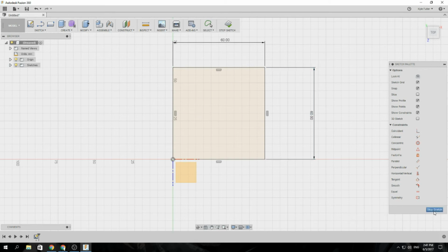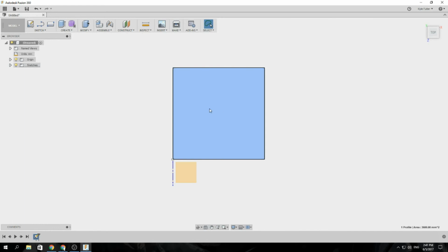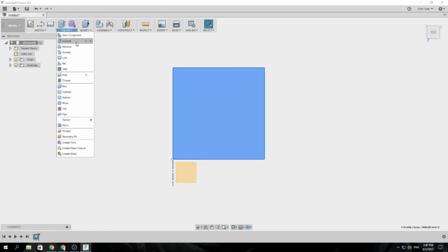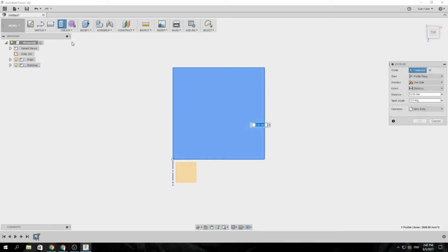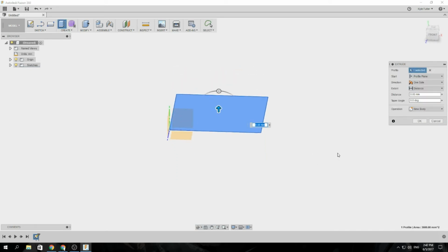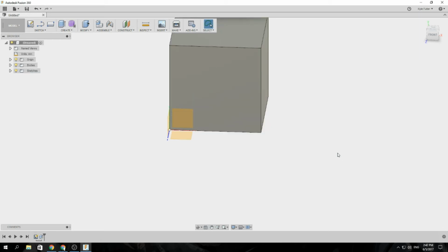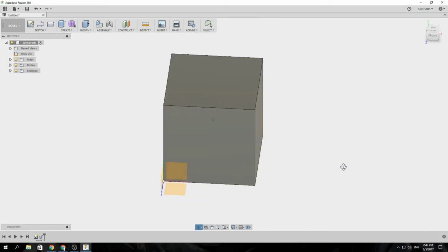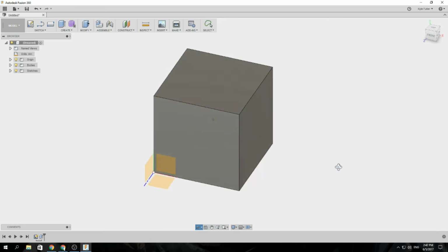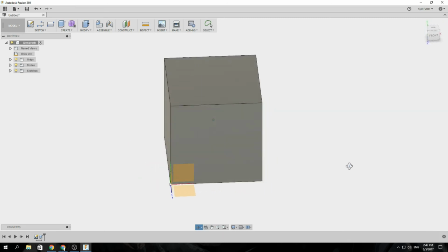Great. So if we go stop sketch, we click on the face, and if we want to go create and extrude, there you see where it's got extrude, next to it it's got E. That basically means you click E, it'll activate that. We've got extrude, and we'll make it 60 millimeters. Just arbitrary numbers, but yeah. So there we have a 60 millimeter by 60 millimeter by 60 millimeter cube.